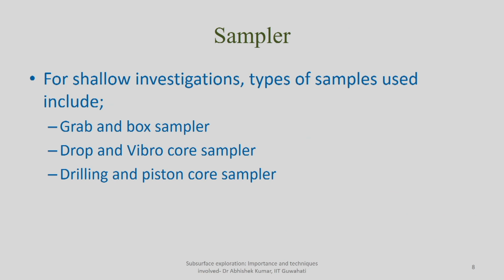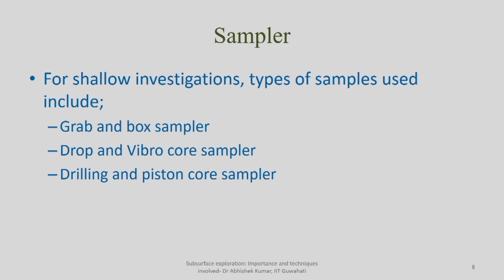Now, we discussed that in the offshore environment, if there is some variation in obstacle or topography, you go for detailed investigation. Then we have to collect samples, because finally you bring some sample into your laboratory to go for determination of moisture content, in situ density, strength characteristics, and soil classification itself. So you have to have some kind of sample in order to characterize the medium in detail based on laboratory investigation. So, samplers for shallow investigations: